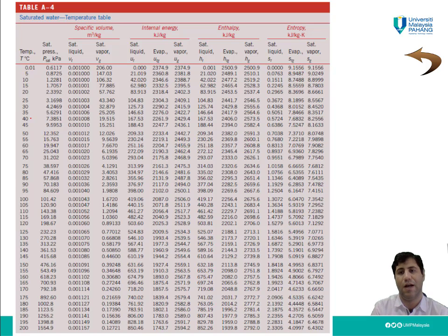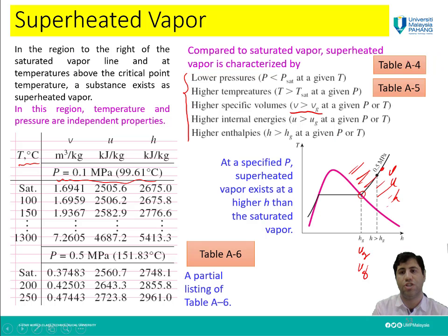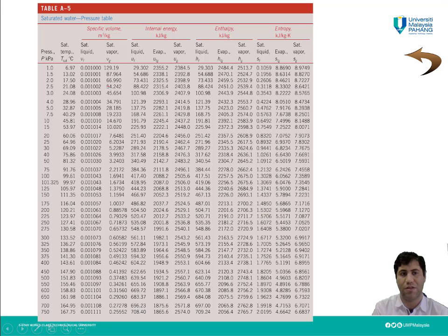Interpolation is a method which also applies to other tables. Let me show you the other table too. You can see here 4 kilopascal, 5 kilopascal, and so on. 10, then 15, 20. What about 18 kilopascal? How can we find these properties for that pressure?